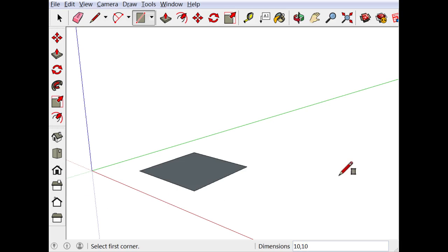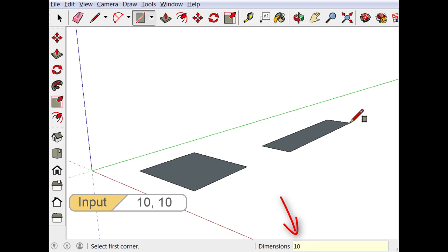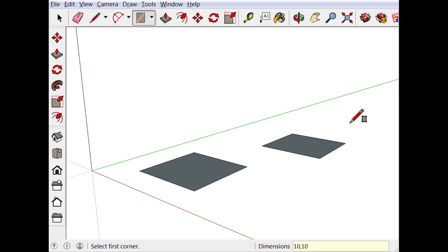With SketchUp, while drawing a line or figures, we can click on the start point, drag the mouse out, input dimension numbers, and then press enter. Steps are the same as the way we have just learned. Or we can draw a figure randomly first, then input the dimensions we want. The 2 ways are alternatives and both correct.